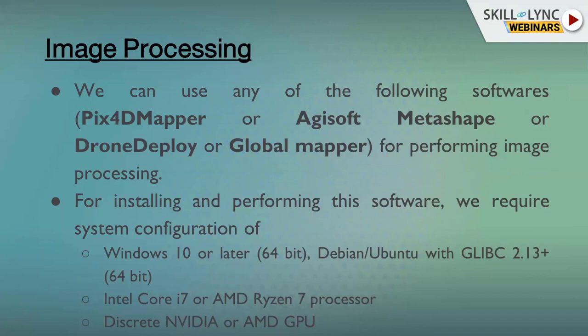With the help of the ortho-rectified image, we can plan the mapping, asset mapping, all those things. Other than the ortho-rectified image, we will get a digital elevation model, digital surface model, digital terrain model, contours and point cloud data. With the help of these data, we can do multiple analyses according to our requirement.